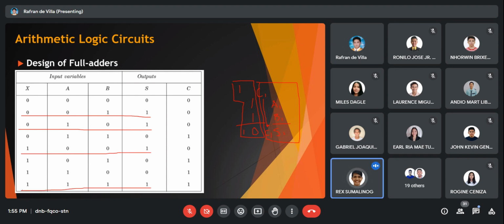If there are odd numbers of 1s... So actually, that is one definition for the output of an XOR gate. Our earlier definition of the output of an XOR gate is that if the inputs are not the same, since we are only limited to two inputs, the output is 1. However, we didn't consider what if there are multiple input XOR.